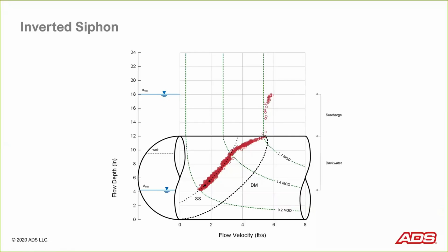So if you do the math there, 1.4 million gallons per day running full through an 8-inch siphon barrel gives you a barrel velocity of 6.2 feet per second. Now, for those of you that have operated siphons or designed them, typically the target value is 3 feet per second in the siphon barrels. So this one, when it's running full capacity, actually exceeds that. That's a good thing.